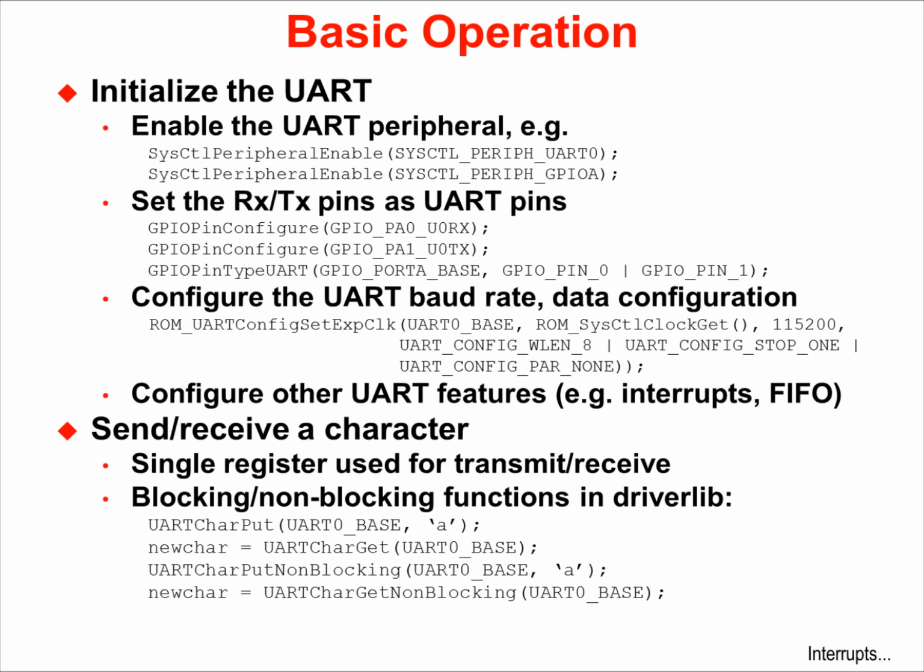In this UART design, a single data register is used for both the transmit and receive functions. The peripheral driver library supports both blocking and non-blocking APIs for writing and reading the data register.